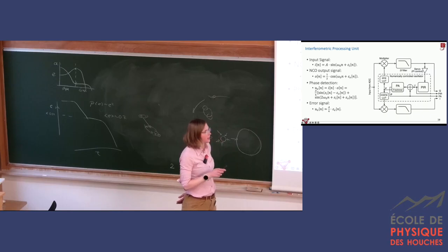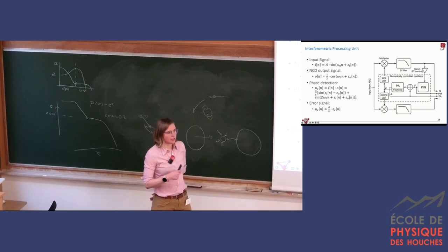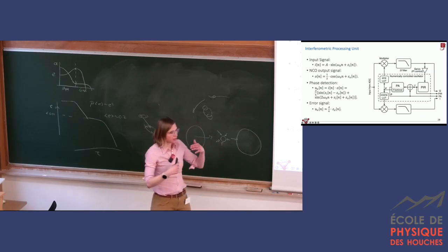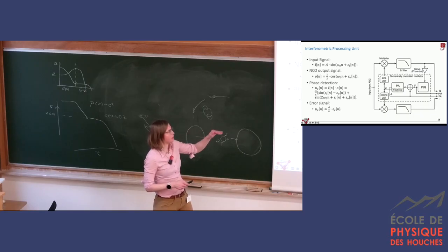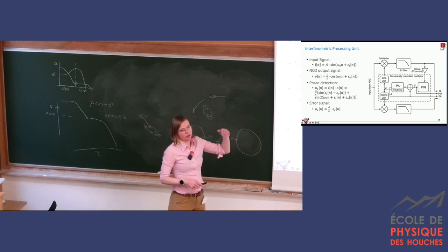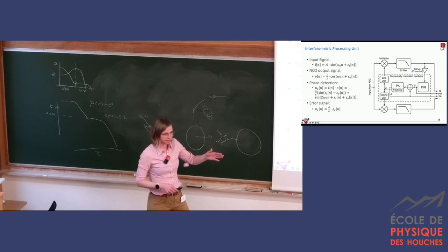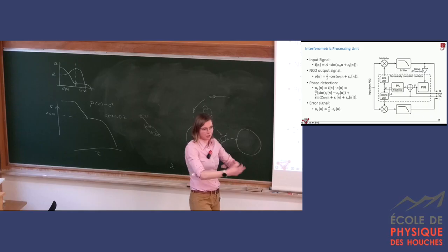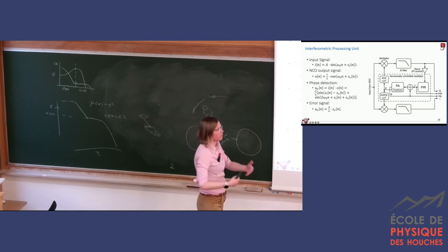The frequency here is in units of cycles, and the phase in units of radians, and they depend on this quantization number n, where the difference between this sample and the sample that arrives at time n+1 is 1 over the sampling frequency. Later in post-processing, we'd have to reverse it to get back to hertz and actual phases.